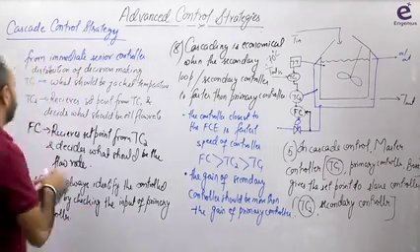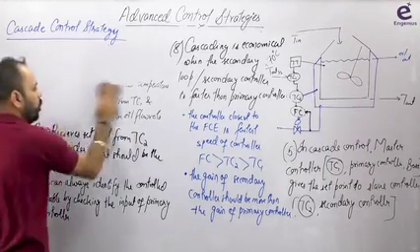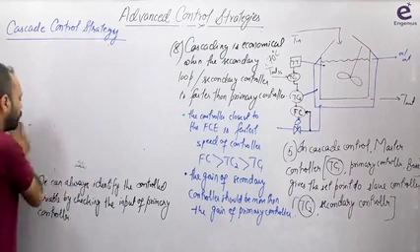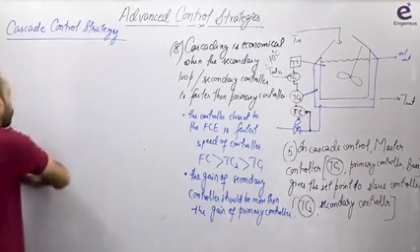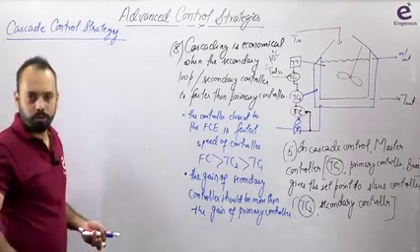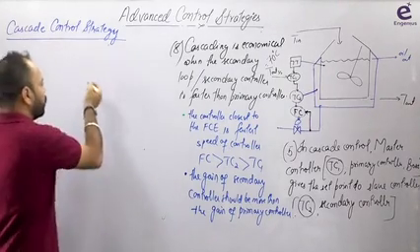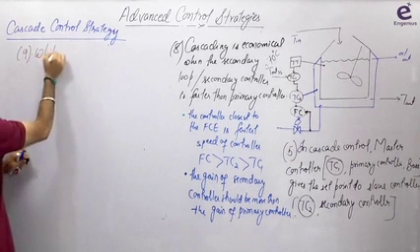One more point, while tuning. Now when you are designing a cascade control, you do the tuning. So while tuning, the inner loop should be tuned first, and thereafter according to the dynamics of the inner loop, the outer loop, meaning the primary loop, should be tuned. So write this point down. You will say, sir, how did we find this out? Some things you also have to remember, not everything has to be explained. Write this down: while tuning a cascade control loop,